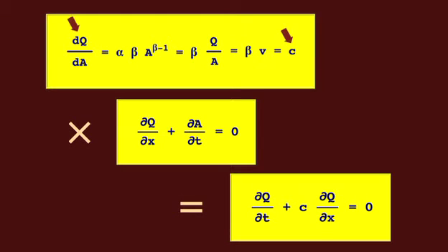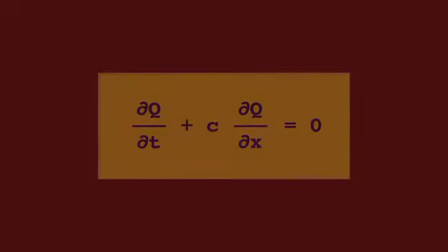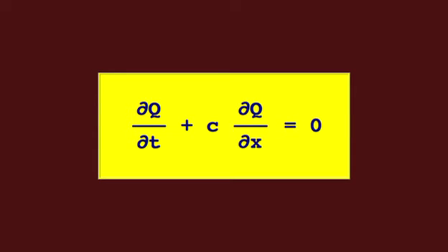Multiplying the kinematic wave celerity with the water continuity equation and applying the chain rule leads to the kinematic wave equation. Note that the kinematic wave equation is of first order. Therefore, it can describe convection, but it cannot describe diffusion. This fact has significant implications for flood routing.